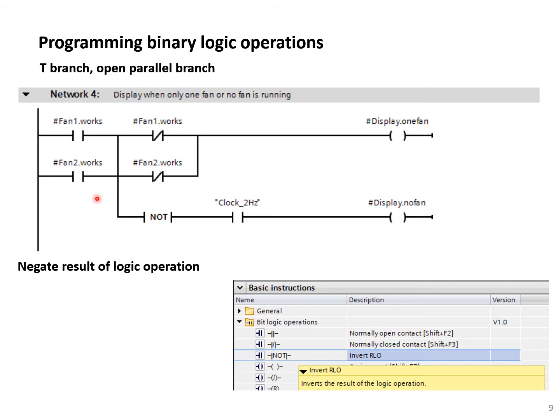Okay, so if this works, we have true here, we'll have false, and then this clock doesn't work because it's false, and then it doesn't flash. But if any of them stop working, then here we will have false and we'll negate it to true, and then we'll start flashing.